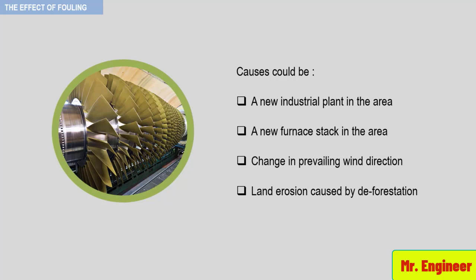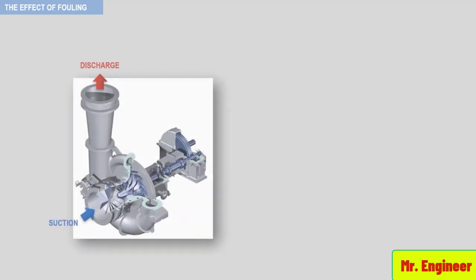One example that comes to mind is a polyethylene plant recycle compressor in which I participated. A new 30% larger recycle compressor was installed, and immediately after startup, the entire compressor was fouled with fines and polyethylene resins. The previous recycle compressor had not fouled in 10 years of operation. The following figure will show you the removed rotor after only 1 week of operation.